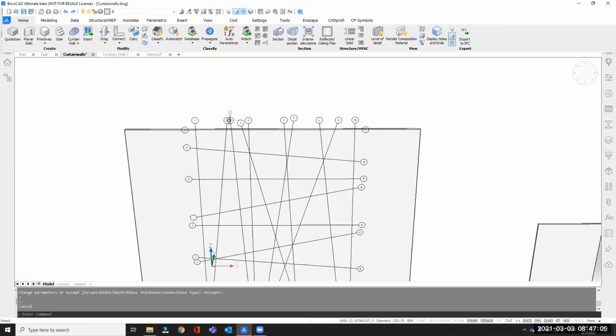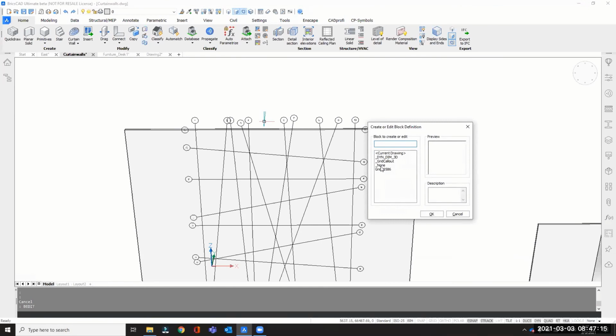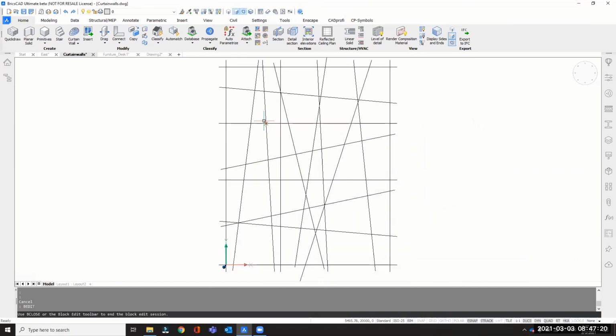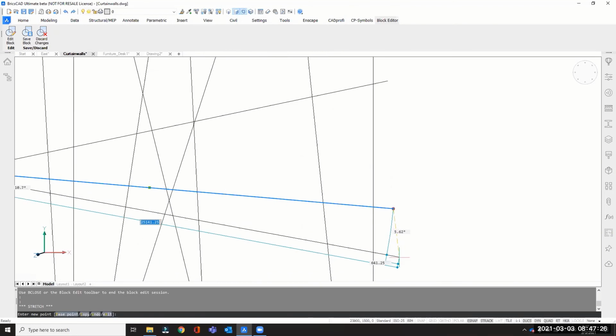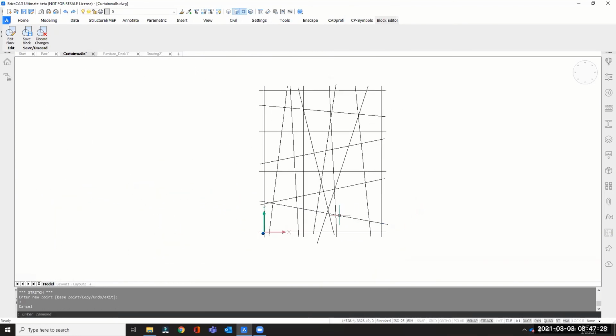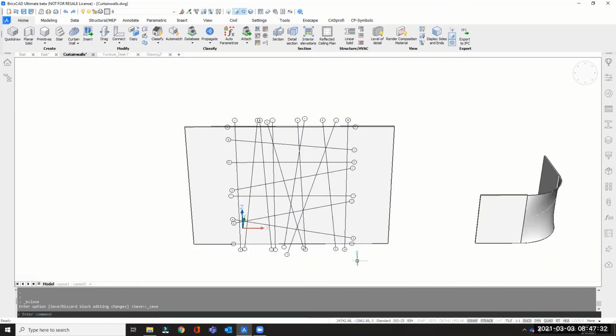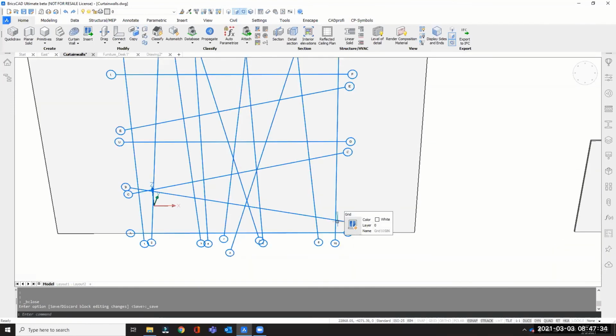This is similar to the type of grid that we were creating earlier, but it was edited. So how do you edit it? You can actually go to B-edit and select the grid. This is the grid that we are looking at, and you'll be brought into the grid. You can actually shift this around. Let's say we just shift it here, and then that's maybe the change we want, save the block. And you'll go back to this grid and you remember that we shifted this certain line.